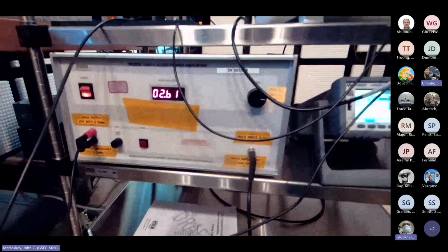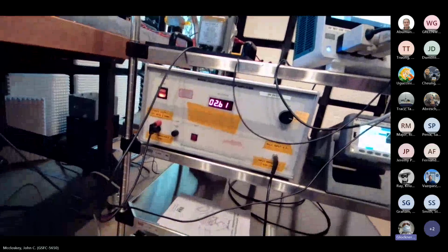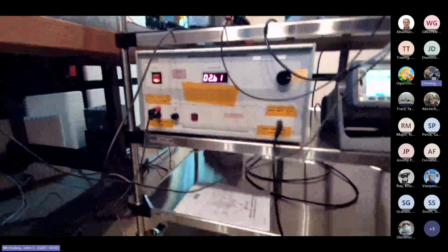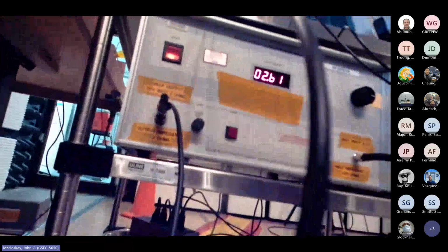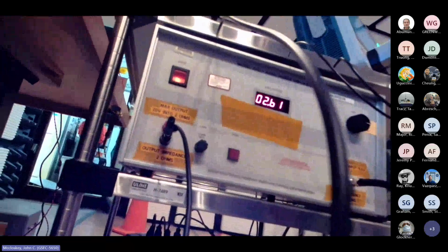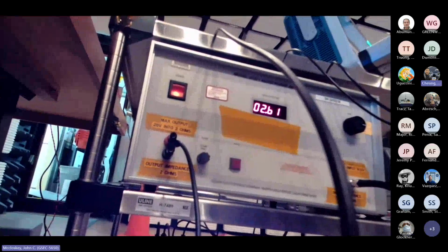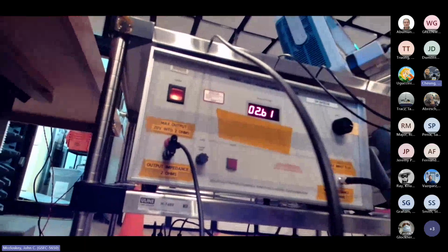What's the source impedance on the amplifier? Do you know? Well, that's going to be central to the discussion. It's actually shown down here: output impedance of 2 ohms, at least as advertised. That probably does vary over frequency, and that's one of the things I'm going to show you.